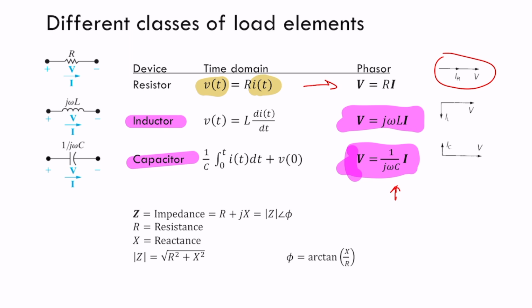If we represent those vectors, V and I, as complex numbers in the complex plane, we see that the current is lagging the voltage, or we can say also that the voltage is leading the current. This is something very typical for electrical engineers, who are very used to saying that. Something similar we have for the capacitors. In the capacitor we will have just a linear relationship between current and voltage in phasor or frequency domain.